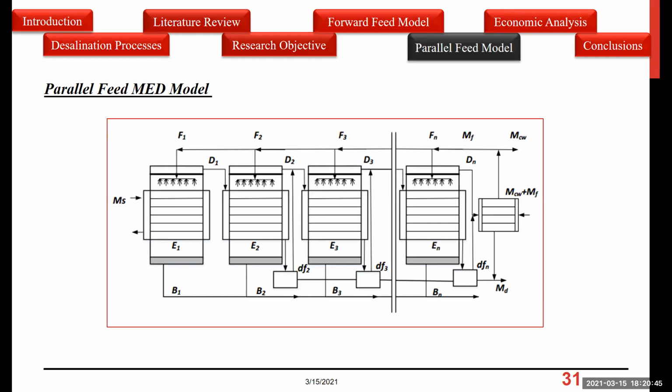So it's consistently showing that the best performance for the ejector is when it's connected to the middle of the system that we have. That was for a forward feed system. Then in a visit to my office, he was showing the results. I said, fine, we could see that for the forward feed. Let's have a look at it in the parallel feed and see how the performance is going to be. And he did the analysis for the parallel feed. What you see in front of you is a parallel feed MED system with flash boxes, but no preheaters.